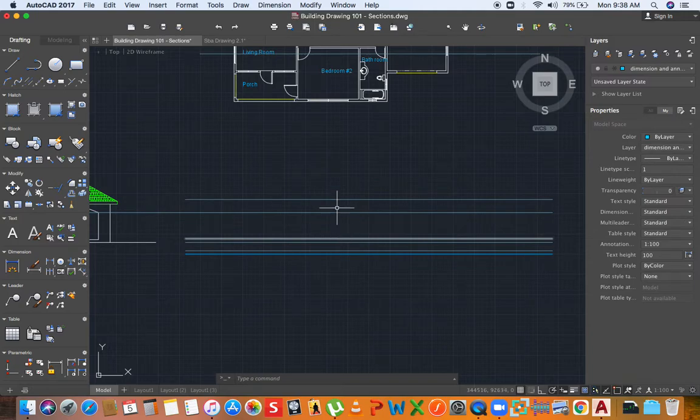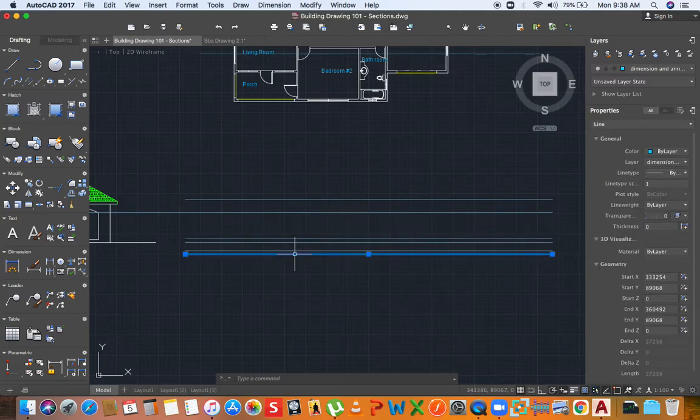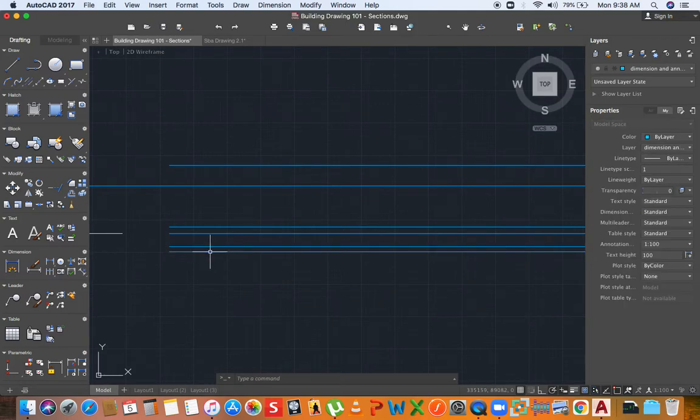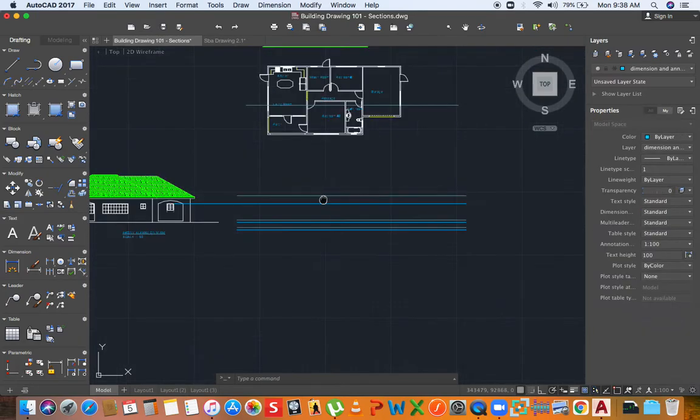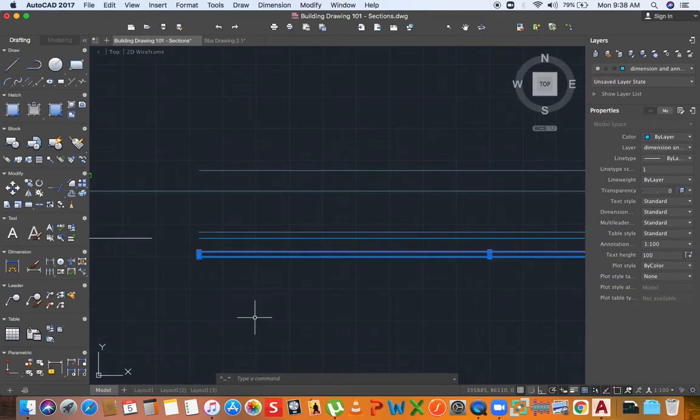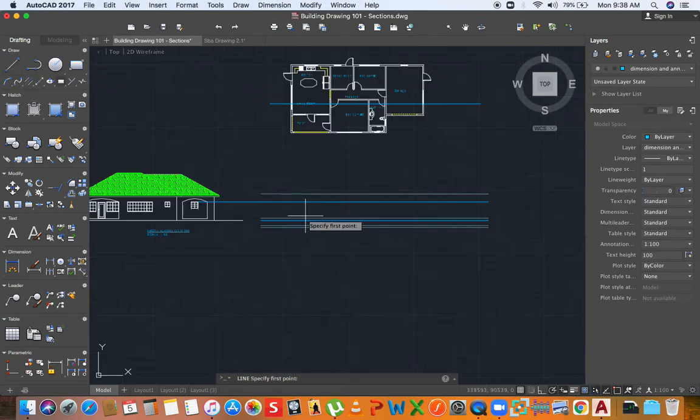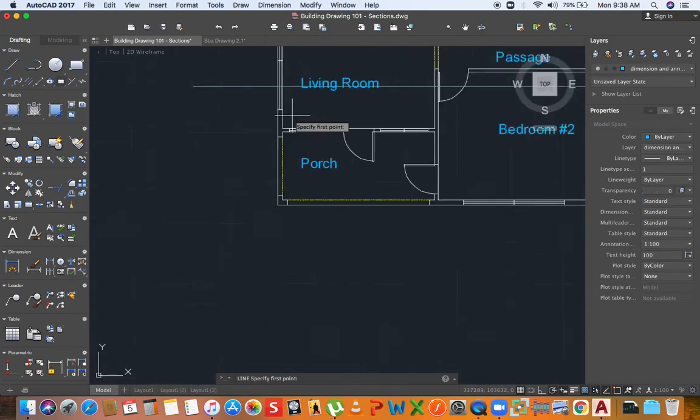You already know that from the elevations. Ground level, and then you have the depth of the foundation, and from the depth of the foundation you offset 250 millimeters for the foundation footing thickness. So you have these two extra lines here that are separate from the elevations. Then this is what I'm going to do.